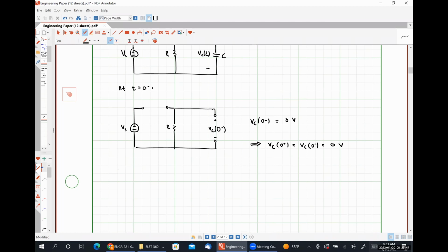All right. So now let's look at what happens at t is equal to infinity. In all of our previous examples, because we disconnected our source, our signal decayed to 0 at t equal to infinity, because our capacitor or inductor, whatever our energy storage element was, completely discharged all of its energy to the connected resistance, and that resistance turned that stored energy into heat.